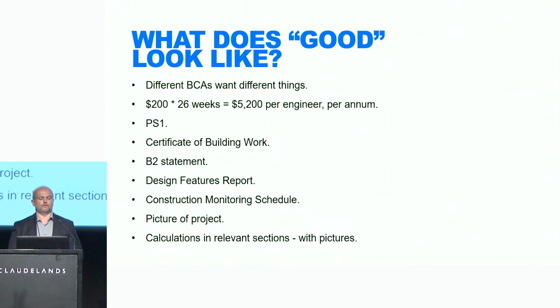Construction monitoring schedule: I saw very little evidence of construction monitoring schedules on the work that I was inspecting. We need to make sure that people are aware of who's going to be inspecting the work that we're designing. The builders need to know when to call us.